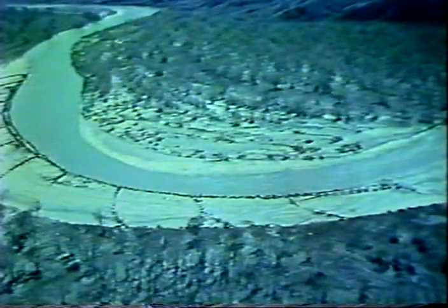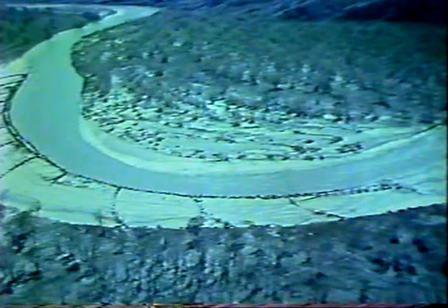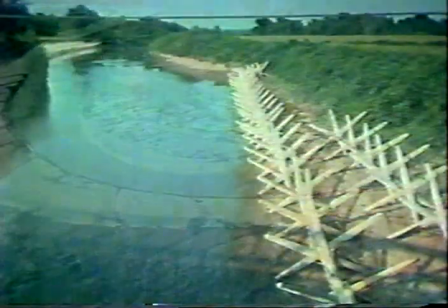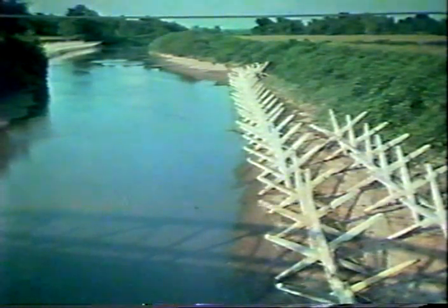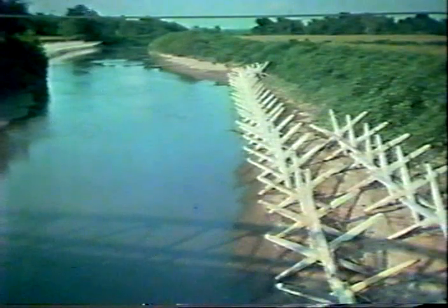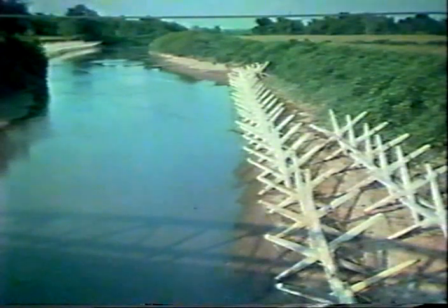This bend on the Cheyenne River in South Dakota has been successfully stabilized by a jack field. Among the requirements for good performance of jacks is an adequate load of sediment and debris in transport by the stream. Jacks used by highway agencies are usually made of steel, but these jacks installed by the Soil Conservation Service on the Tallahatchie River in Mississippi are made of concrete. Good performance of the jacks in stabilizing banks is